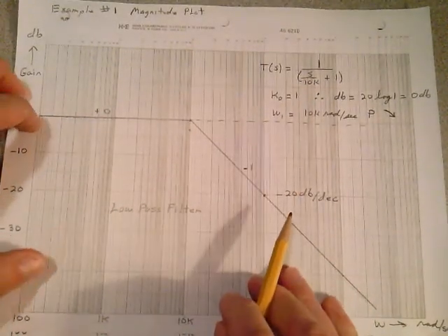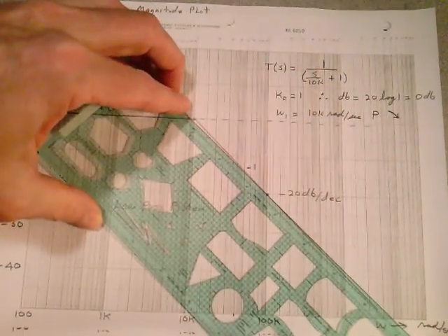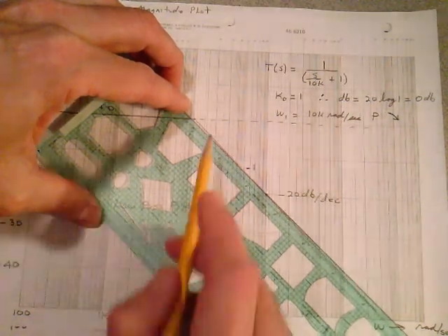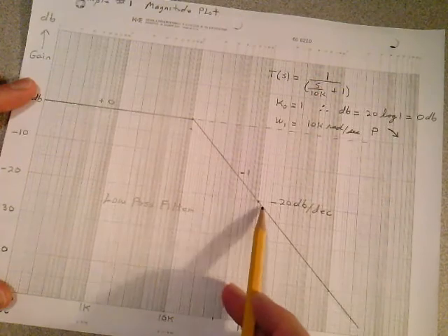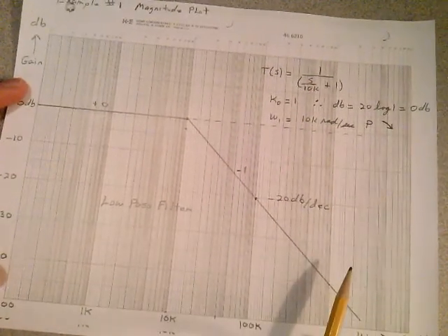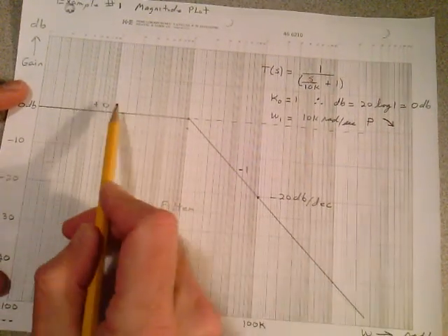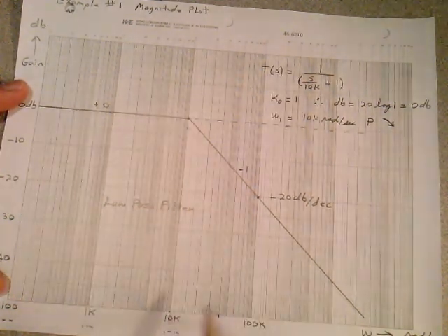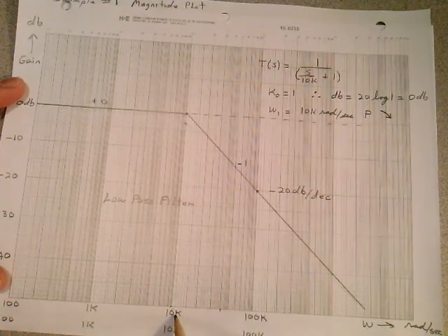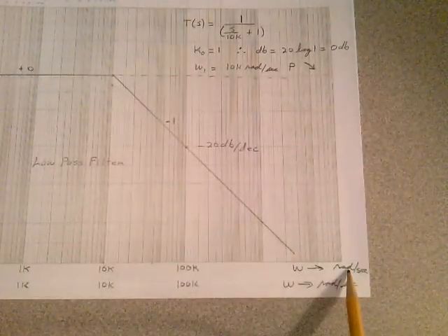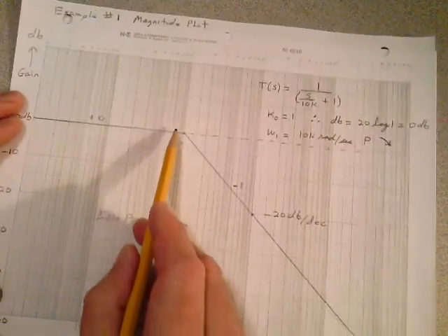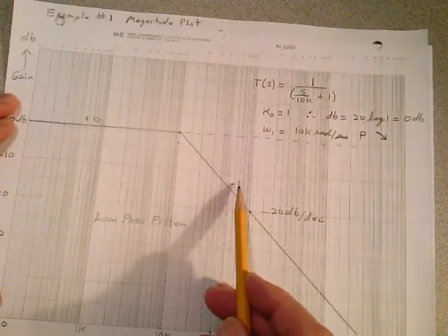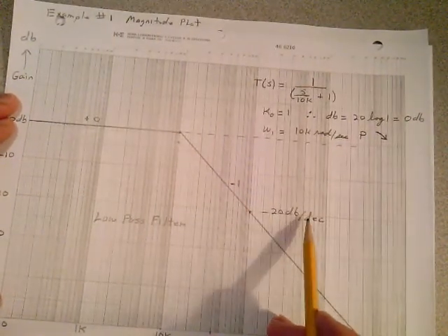And I get my straight edge. Once you get your straight edge and you line that up, you put a dotted line in from that point down to here. You put a dotted line in from here the whole way down through. And that's your 20 dB per decade slope. So I mark this at a 0 slope up here, and at that break frequency at 10K radians per second, and I label all that down here, I get a roll off of -1. That's the shorthand notation. We know a -1 is a minus 20 dB per decade.